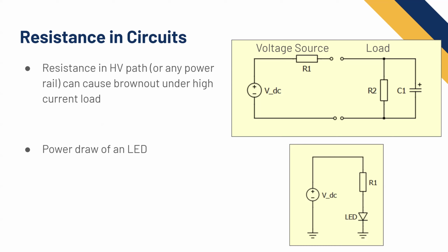And so this tells you the power, and then you can get the total energy consumed if you multiply it by time. So let's say we ran this 20 milliwatt LED for an hour, the energy consumed is 20 milliwatt hours. Milliwatt hours is power times time, so it's like energy consumed. And the LV battery that we have right now is 20 amp hours. They also measure in amp hours. But if you multiply amp hours by the nominal voltage of the battery, you can get watt hours, right?